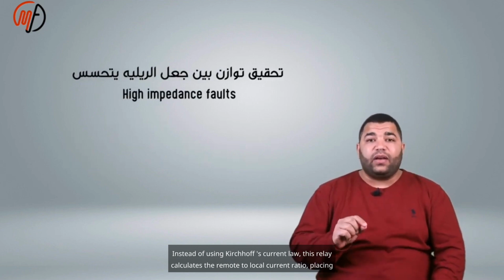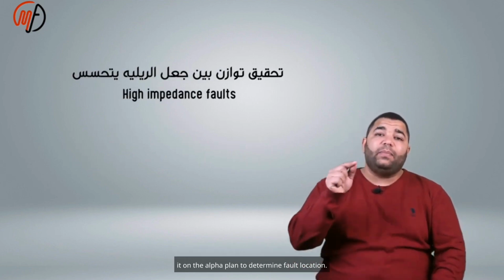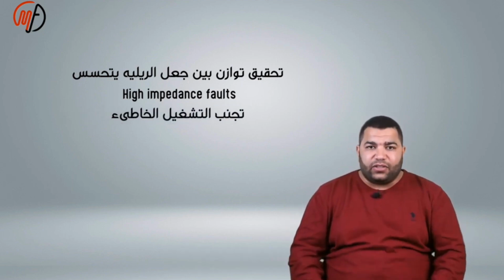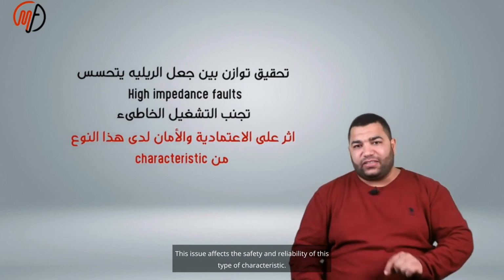Instead of using Kirchhoff's current law, this relay calculates the remote to local current ratio, placing it on the alpha plane to determine fault location. All current values are directional, considering both magnitude and angle. This issue affects the safety and reliability of this type of characteristic.